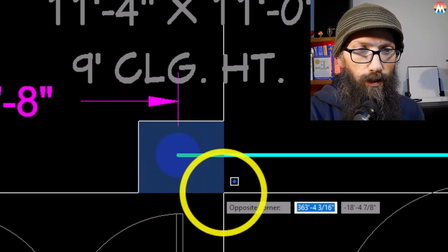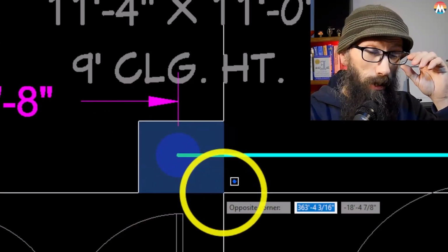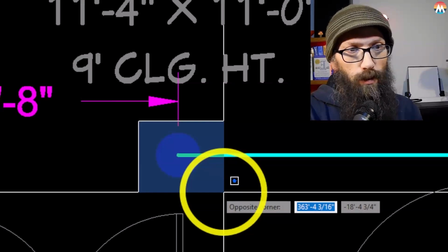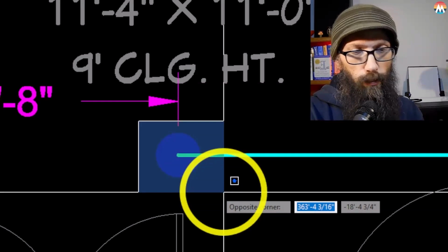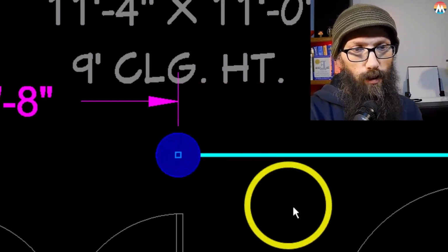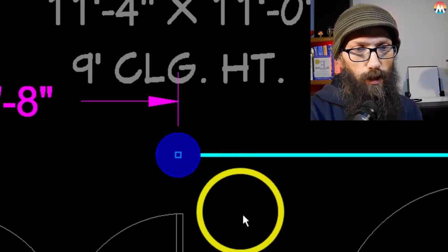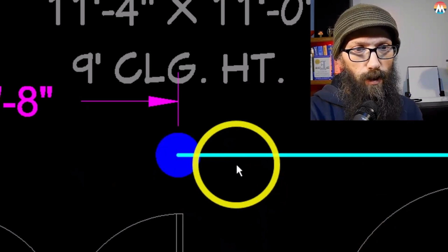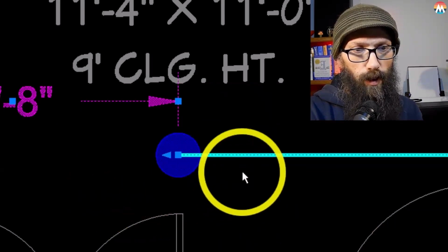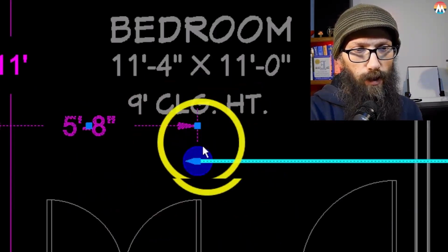You see now, instead of the dashed line, I've got a solid line and it's blue inside. It's doing those differences to remind me that there's a difference between the two. When I do left to right, you'll notice it only selected the head. But if I hit escape and do right to left, it selected all of these things.